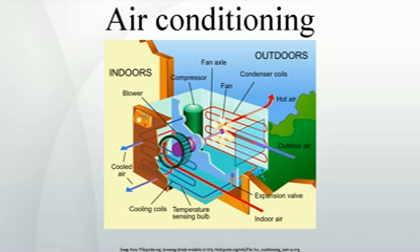Then, for a SEER of 10, the annual electrical energy usage would be. SEER is related to the coefficient of performance, COP, commonly used in thermodynamics, and also to the energy efficiency ratio, EER. The EER is the efficiency rating for the equipment at a particular pair of external and internal temperatures, while SEER is calculated over a whole range of external temperatures, that is, the temperature distribution for the geographical location of the SEER test.